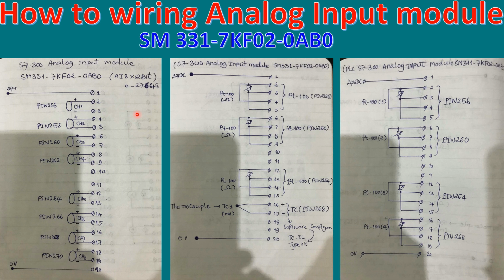Okay, so we need to know how to wire it. So option number 1, we can use a channel of analog input with the default address PIW256 until PIW270. Okay.